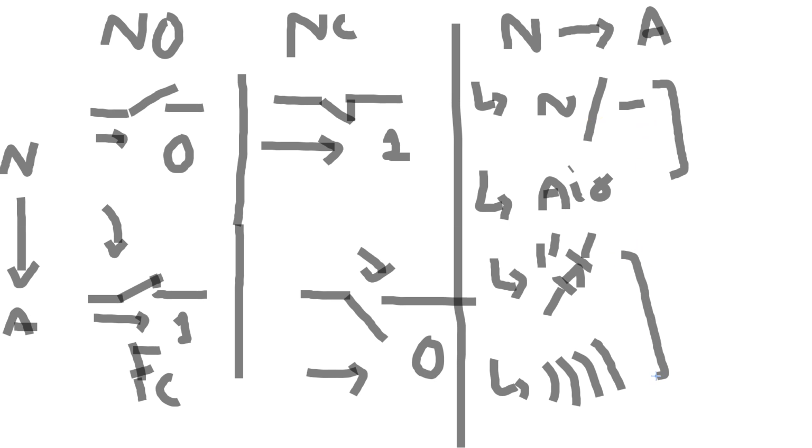The last two are not preferred because they are susceptible to industrial processes. For example, sound can be easily interfered with by the vibrations of the process or the sound of the process. I'm not saying that the first two signals are not susceptible to noise. For example, electrical noise is present all over the plant. Also, a bent air pipe can stop the whole plant. However, these are easy to trace, easy to install, and low cost solutions. So therefore, we prefer the first two signals.